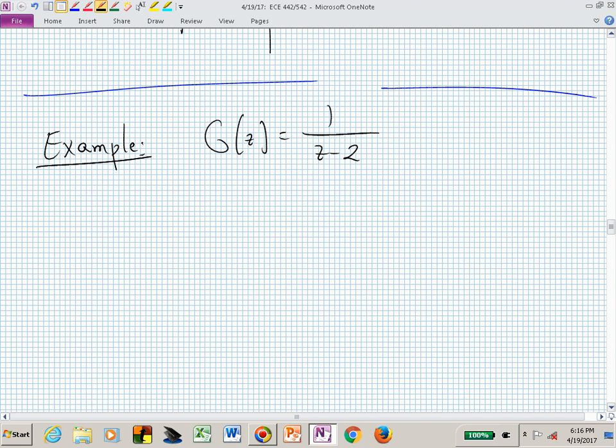It's exactly like the root locus in the last example, except now we're starting at 2. We would now need to have a minimum value of gain k to get a stable system. That would be determined by the magnitude condition, solving for k when z is equal to 1. The maximum k would be when z is equal to minus 1. We have some region of k that we can stabilize our system with.